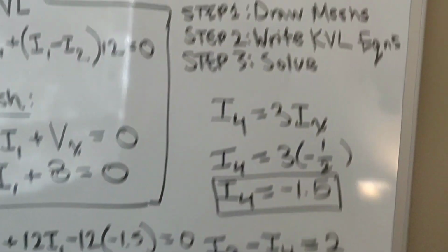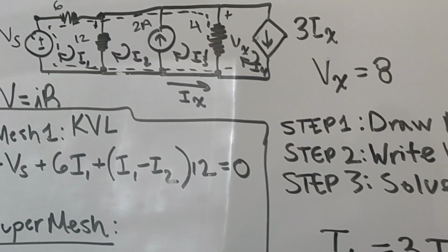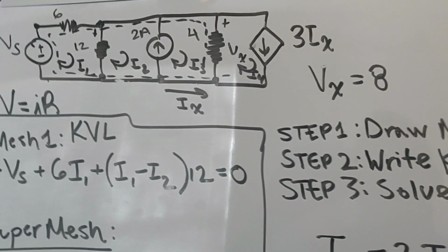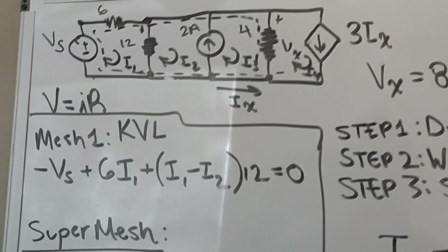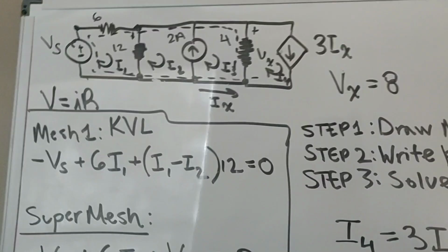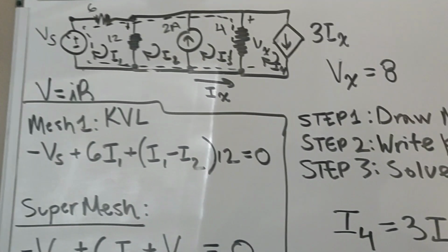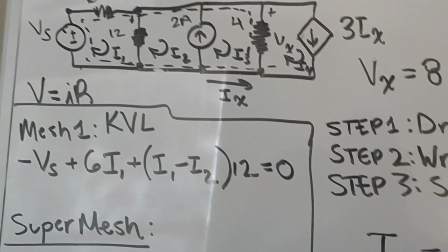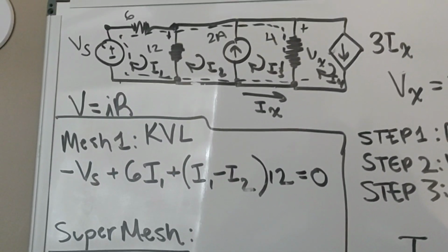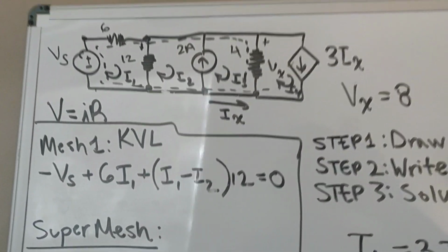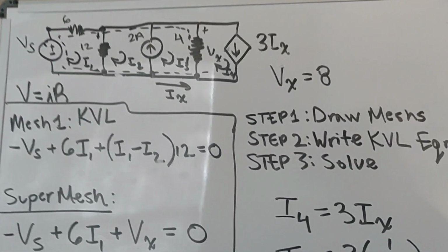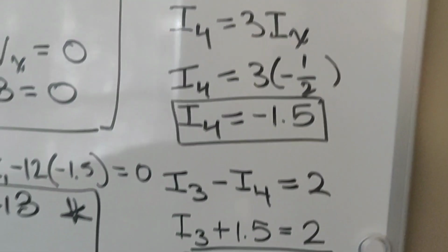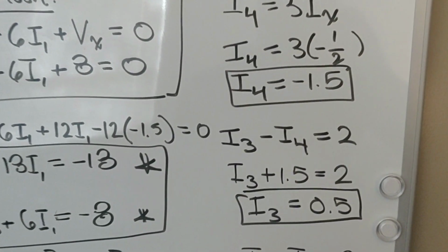We also analyzed the circuit to find constraint equations. Always analyze your circuit when you don't know or when you're stuck somewhere. Analyze your circuit. Try to find some constraint equations using the simple laws that we learned: KVL, KCL, Ohm's law, you know. And that's what we did here to solve for a couple of these meshes.